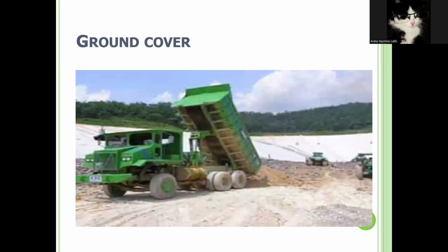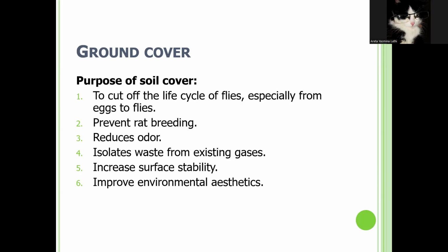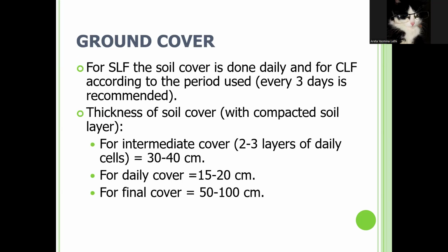And this is the ground cover for the landfill itself. And the purpose of cell cover is to cut off the life cycles of flies, especially from eggs to flies, and prevent rat breeding, reduce odor, isolate waste from existing gases, and increase surface stability. And the last one is to improve environmental aesthetics. And for the SLF, the soil cover is done daily, and for the CLF, according to the period used, every 3 days is recommended.